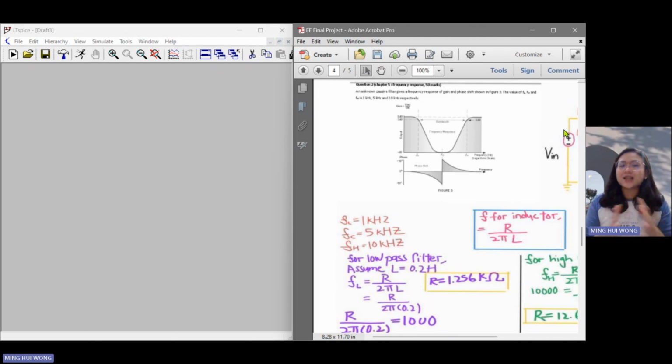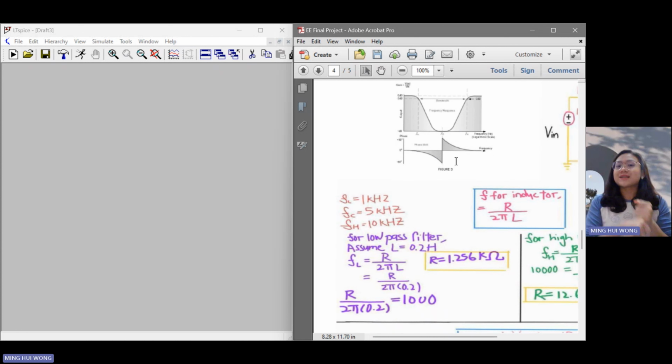In my knowledge, the function of a bandstop filter is to pass all frequencies from zero up to its first cut-off frequency, known as FL, and pass all frequencies above its second, upper cut-off frequency FH, but block or reject all frequencies in between. The filter bandwidth BW is defined as FH minus FL. So let us construct the bandstop circuit based on the data and graph given.